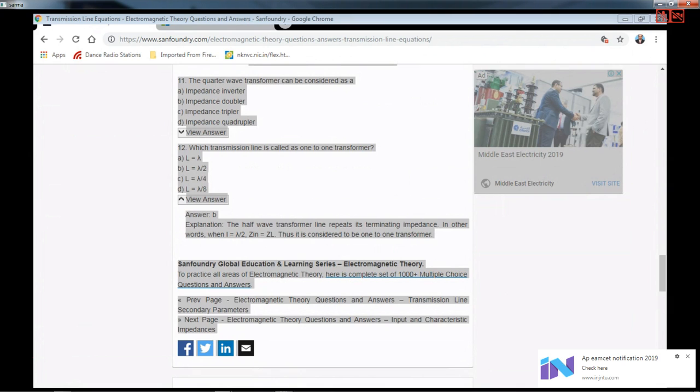As you can see, on a length of a transmission line, the standing wave is going to have several maxima and several minima. And you know very well, if there is any standing wave, the maxima will be spaced about lambda by 2 apart. That means if you identify 2 successive maxima and find the distance between them on the transmission line, it is going to be equal to half wavelength. Similarly, if you identify 2 adjacent minima and find the distance between them, it is also again lambda by 2.